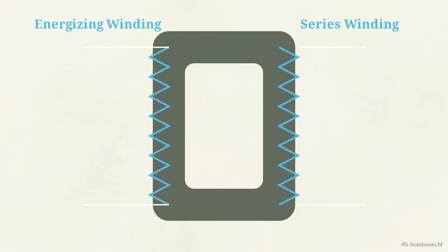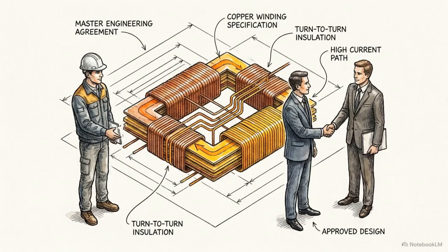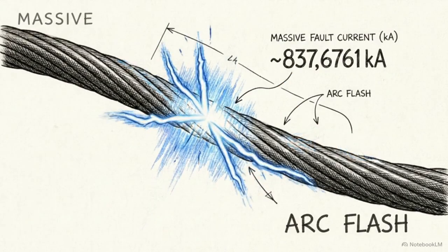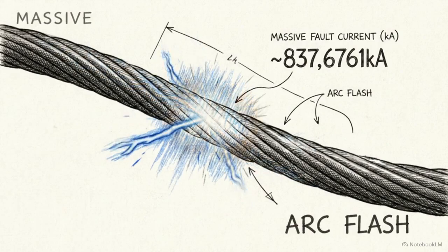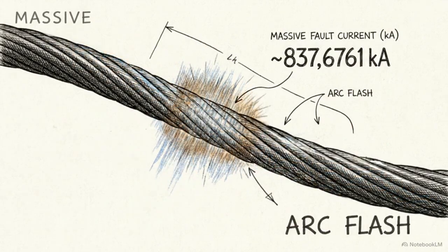Here, an energizing winding supplies power to an independent series winding, allowing operators to shift the phase or alter the voltage mid-line. Transformers often require auxiliary features, like a delta-connected stabilizing winding. This winding is intentionally isolated and never connected to an external circuit. Its role is internal physics management, specifically decreasing the zero-sequence impedance during ground faults to protect the core. Adopting this standardized nomenclature allows manufacturers and purchasers to reach precise technical agreements on transformer function. By defining a winding's type and intended connection, engineers accurately calculate how the system will react to fault currents before the hardware is ever deployed.